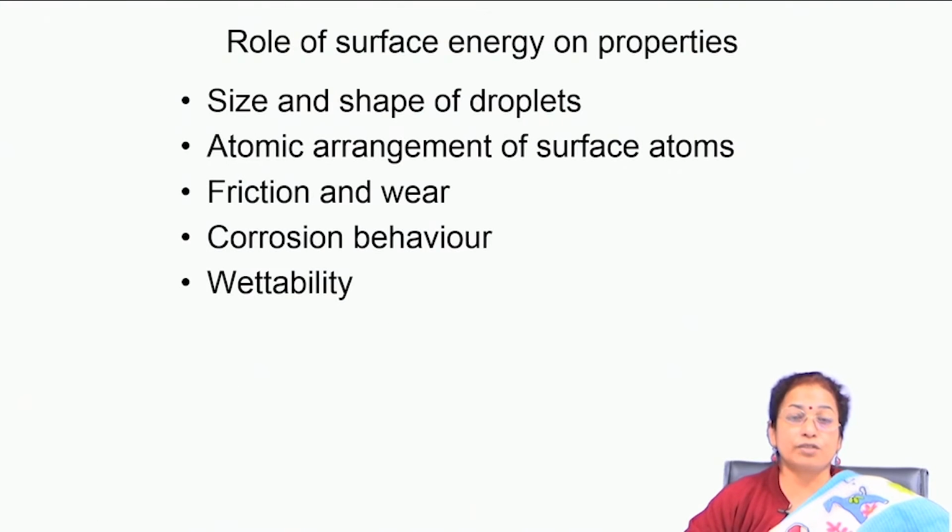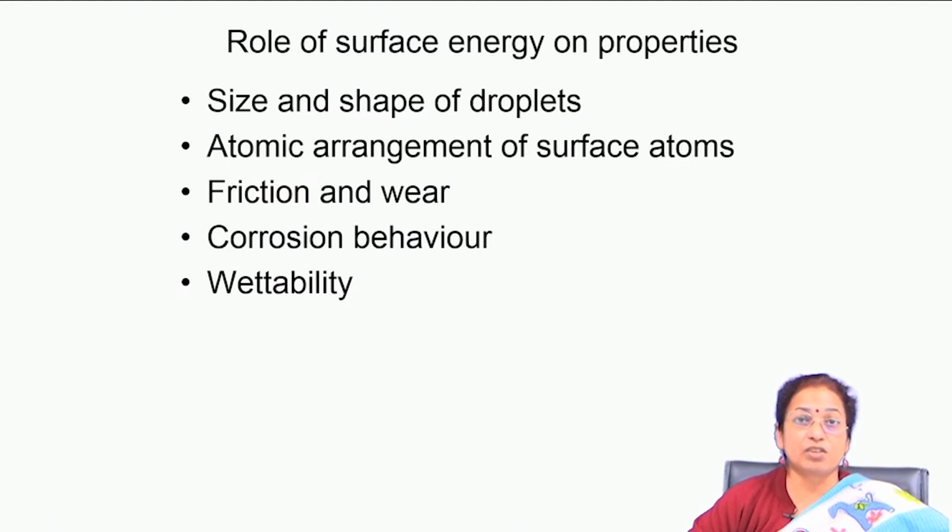Surface energy influences many important phenomena, for example the size and shape of droplets, atomic arrangement of the surface atoms, friction and wear behavior, corrosion behavior, and wettability. All of these depend on surface energy, and the driving force is the free energy change associated with lowering of surface energy. When you create a surface, there is an increase in energy, so naturally the driving force is the lowering of that energy.